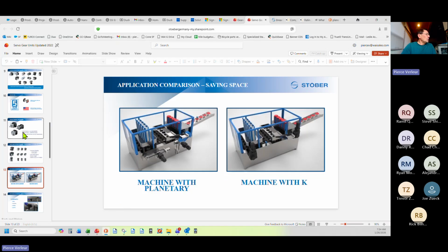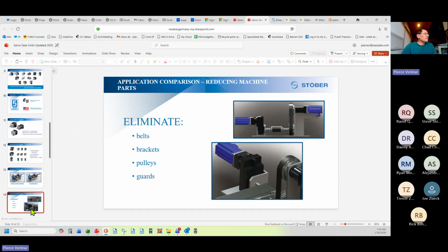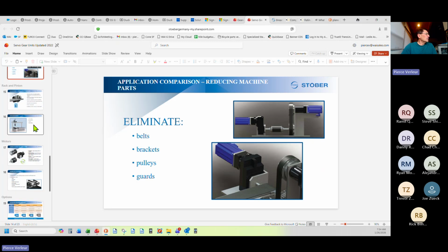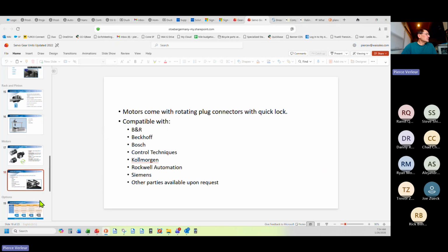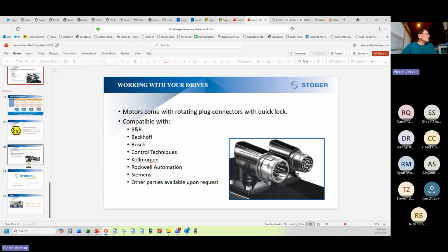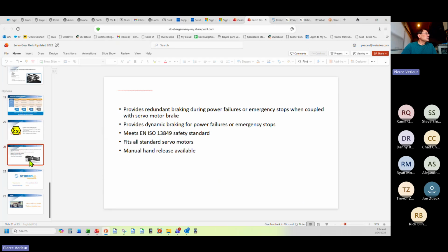Now, when we talk about gearboxes matching up to motors, that's another issue we need to be aware of in terms of sizing the gearboxes. And what I find is that axial length becomes the main factor.